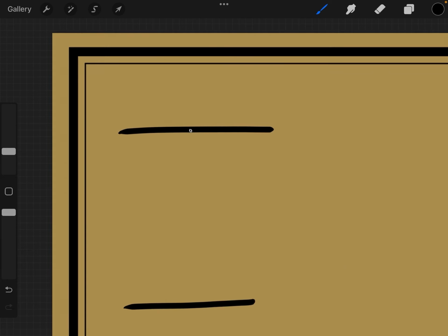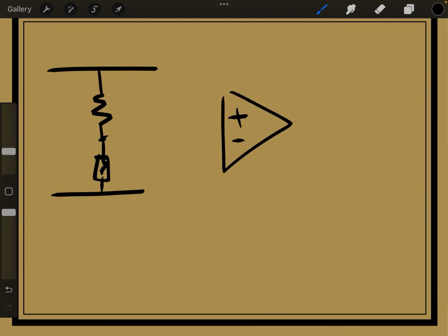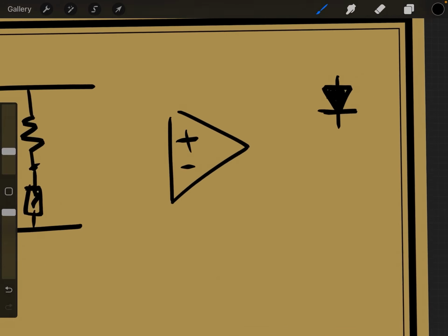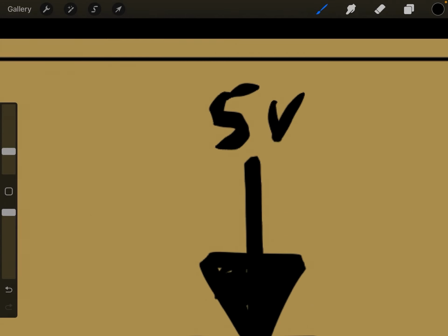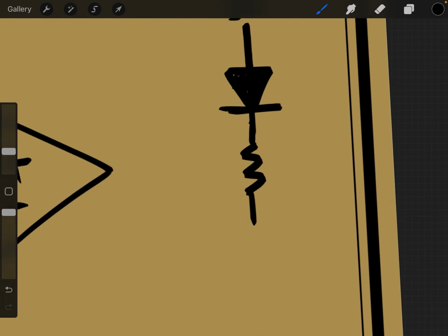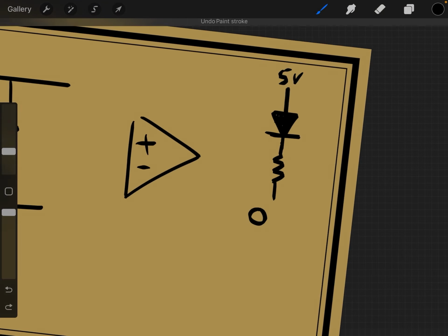So we have a voltage divider where we know that the voltage gets smaller as the temperature gets higher, and we have a comparator here, and we have the light that we want to turn on here. So perhaps we can do it like this. We'll connect the light up to 5 volts, so it won't turn on unless we complete the circuit by introducing